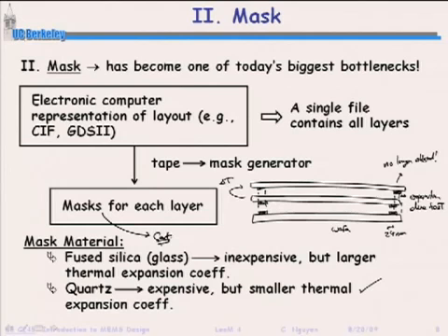And if you don't have a high volume application, that might make sense if you're going to sell 2 million parts and you want to sell them for $1 a piece. Right, it's actually more than that because you've got the cost of processing on top of that, the cost of packaging, right? But if we ignore all those other costs, if your mask costs you $2 million and you have 2 million parts to sell, at a minimum, you can only sell them at $1 per part. Okay? If you had 1,000 parts to sell, you're not going to sell that part. Okay? It's cheaper to make it other ways. Right? So that's the dilemma that we're faced with right now.